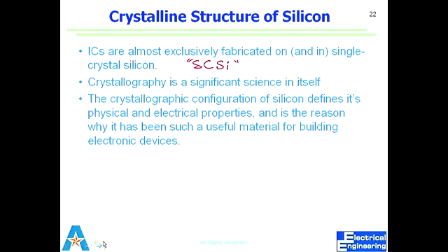Polycrystalline silicon, or what we call polysilicon, is a semiconductor. It doesn't have long range order, it has grain boundaries. So we have some region which has crystalline structure, and then there is a break in structure, and now you have another crystalline part. That break is called a grain boundary.